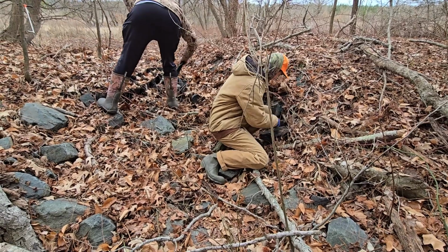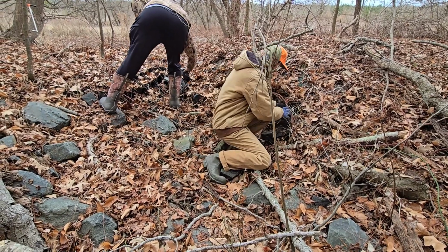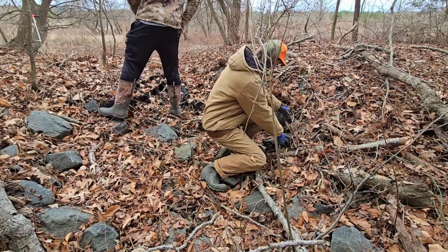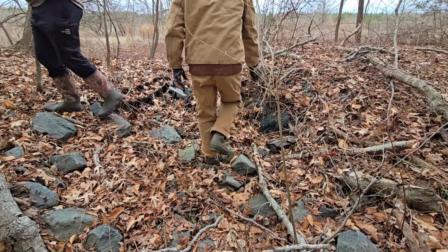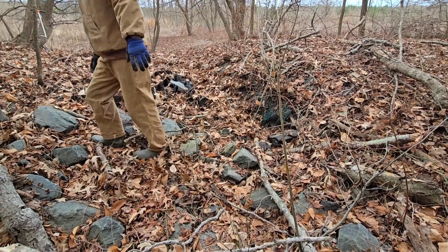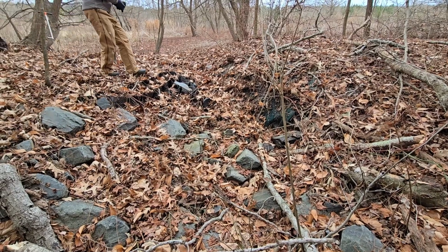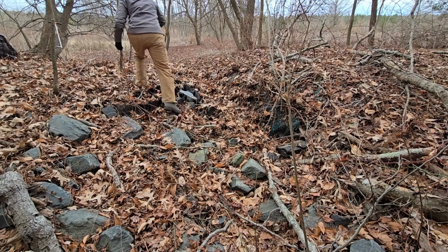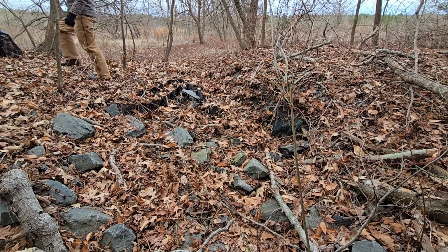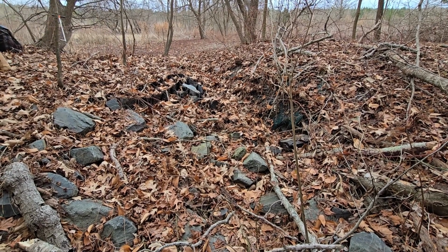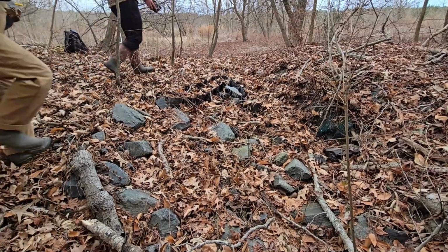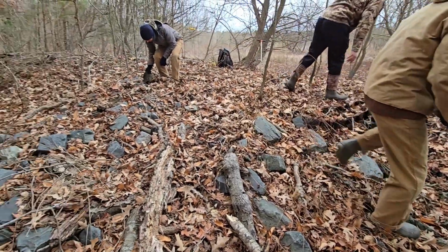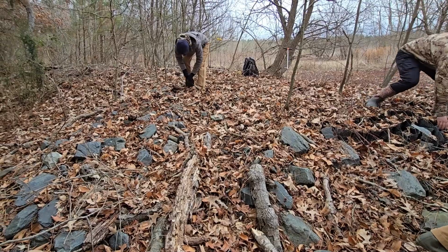Repairing the spillway involves picking up rocks that were dumped on high ground and moving these rocks to where erosion is occurring so that water will flow over the rock. This is like completing a puzzle where you must match the size and the shape of the rock with the surface you're trying to armor. Once the rock is set down, you must move it into position and make it lay flat against the ground. You then stomp on the rock with your feet until it is wedged into position.